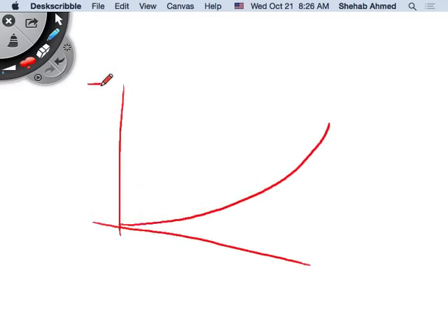Something like this. So this would be torque, and this would be speed for a centrifugal pump. In this case, I don't have torque at 0 speed. There's no flow. I'm not pumping any fluid. And then when I turn the pump, I'm slowly pushing fluid into the pump, and I'm raising the torque. The torque is going higher the higher the speed I go. I'm pumping more. There's more torque required to pump more at that point.